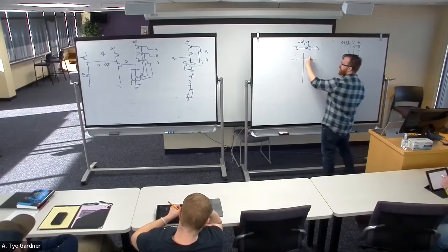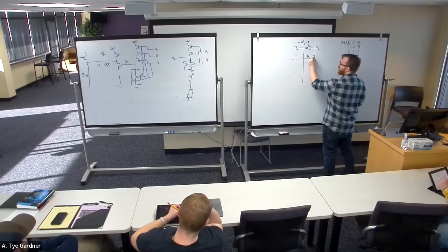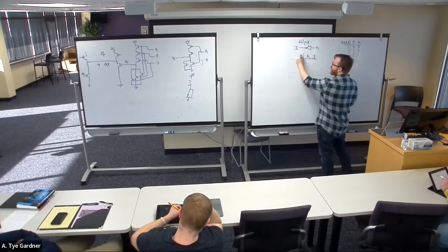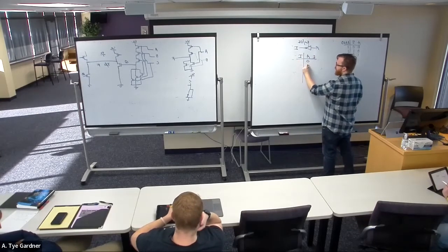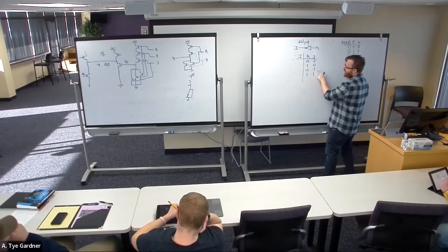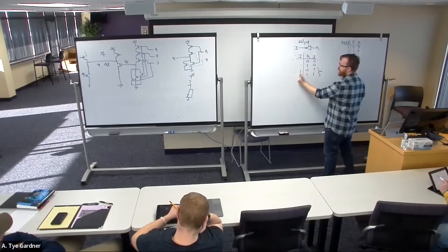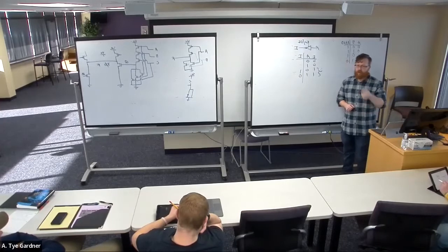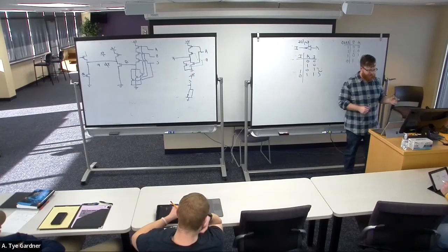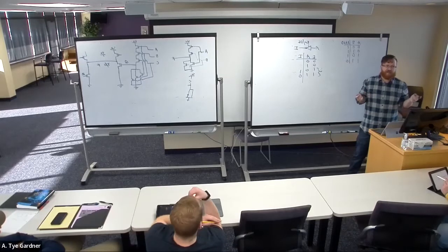Normally an inverter only has A, right? But in this case, I've added a new input, E, or EN or OE. And in the case of this 0, 1, 0, 1, 0, 0, 1, 1. Well, in the case where I am enabled, it just acts like an inverter on A. 1, 0. It inverts A. But when I'm not enabled, it's not connected. What is it?